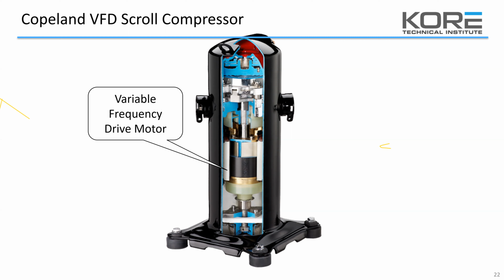or a screw compressor. Those types of compressors do not rely on gravity or inertial energy to do what they do. They have mechanical valves and means of moving gas, so they can throttle up and down and spin a lot faster, a lot slower than what a scroll can do.